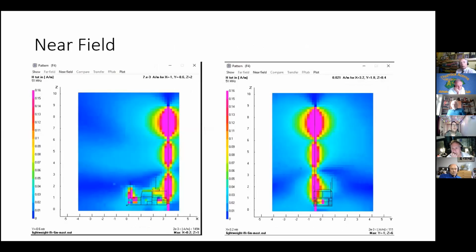What was actually much more interesting about that model: I modeled the Land Rover as plates and rods for the roof frame. I kind of expected parasitic radiation off the antennas on the wing boxes, which happened. What I wasn't expecting at all is that the mast actually acts as a collinear element, and that purely works from the electric field off the end coupling into the mast, because I modeled it actually isolated from the mast.